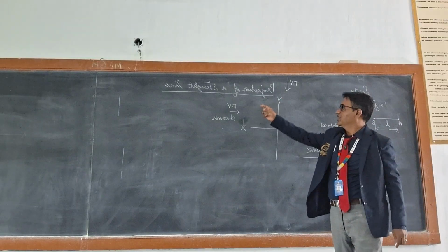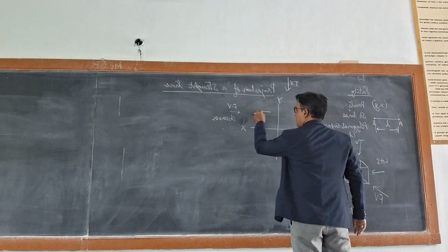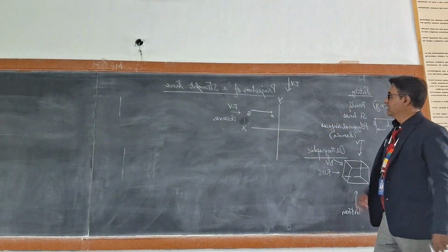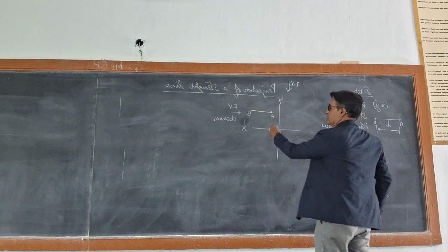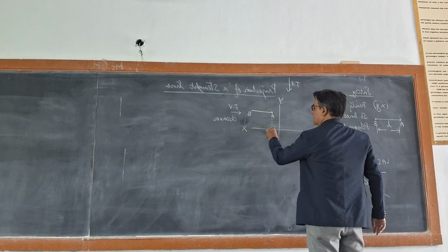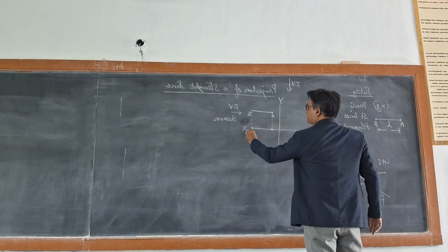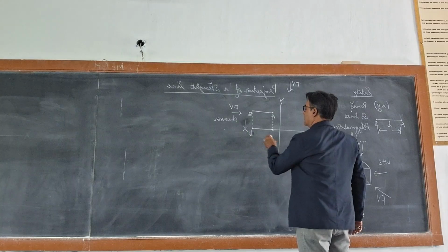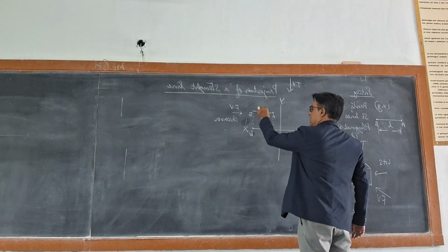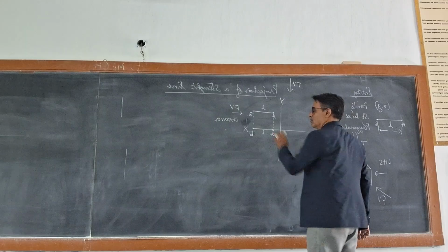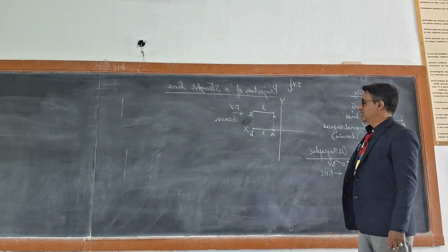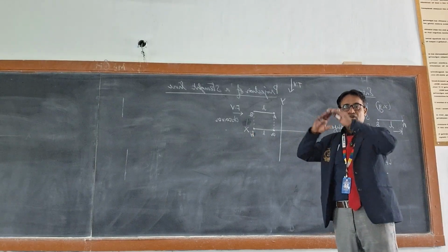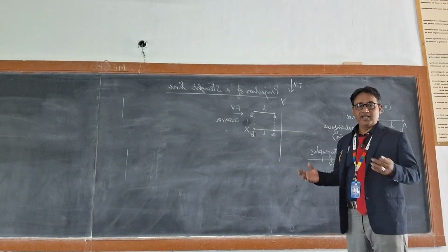Now, when I say I am looking at an object, say for example, a line AB, when I am looking from the top, this A will be projected onto this and B will be projected here. And the projections are marked in lowercase letters, say ab. The length is the same because it is parallel to the x-axis. But when I am drawing this, I have to project all these projections onto an A4 sheet, which you call a plane, right?